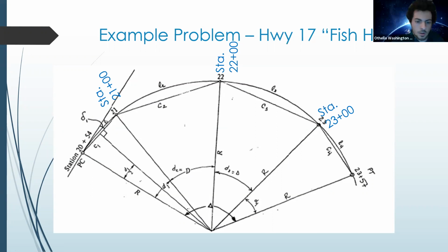So wouldn't that be around 300? Oh, I see, Olga. Yep. Right, okay, got it. Remember with stationing, you just drop the plus sign. You keep the decimal point, but you drop the plus sign and look at it as a whole number. So yes, 2357 minus 2054 gives us 303.